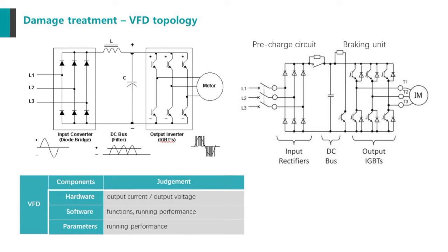And some customers may wonder about the difference between a solar pump inverter and a PV inverter. This is also one big difference. The PV inverter outputs a pure sine wave, but the VFD outputs a PWM sine wave. So the PV inverter is quite different from the VFD inverter.